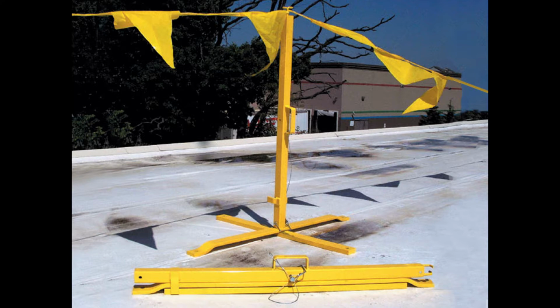Warning line systems. Warning line systems shall meet the following requirements. Erected around all sides of the roof work area. Erected not less than 6 feet (1.8 meters) from the roof edge where mechanical equipment is not being used. Points of access, material handling areas, storage areas, and hoisting areas shall be connected to the work area by an access path formed by two warning lines. Consist of ropes, wires, or chains and supporting stanchions erected according to OSHA 1926.502. No employee allowed in the area between the roof edge and the warning line unless working in that area.